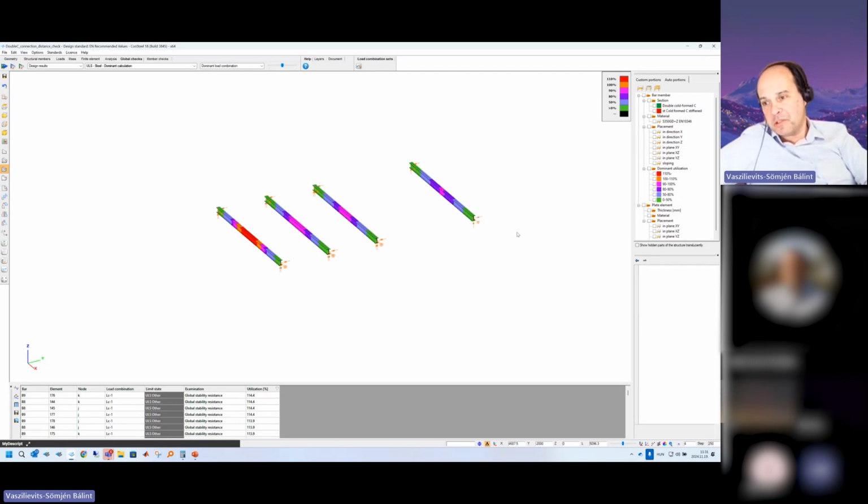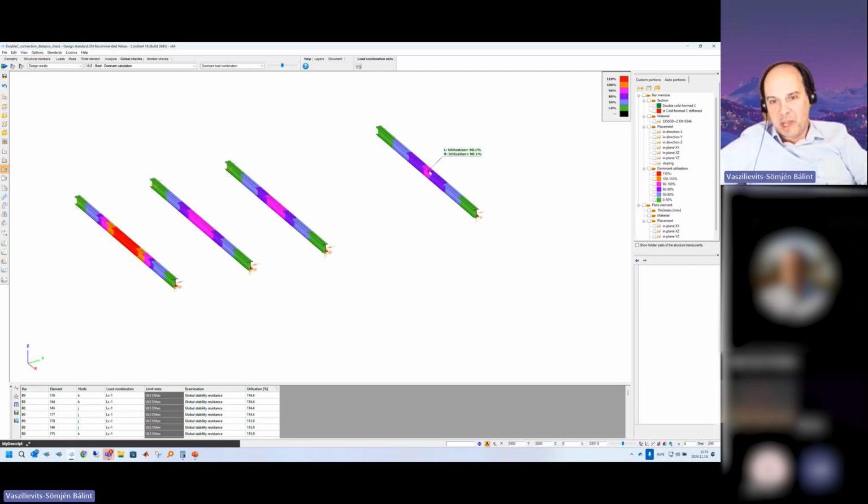The only difference was the connectors. When I used the new unified section approach, I got a 90% working ratio, and the one with the biggest distance, not continuous but with some degrees of freedom released, gave up to 114%. So obviously it has an effect.